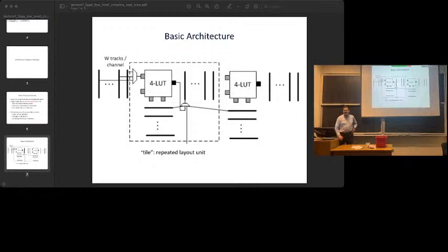Yeah. I think for the connection between the lookup table and the multiplexer, as a designer, we want to guarantee the functionality, the correctness of the design, right? So I think the lookup table itself is not smart enough to determine. Oh, well, the CAD tool chooses this. The CAD tool will choose what SRAM bits to put in here. So this is a 4-to-1 mux. So I could control it with 2 SRAM cells. Maybe I'll use more, but I could control it with 2.